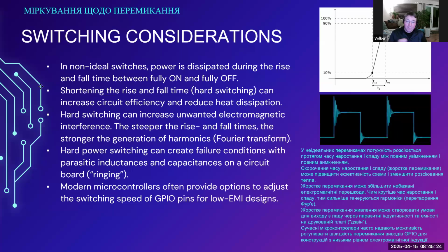In one of the other pictures on the right-hand side, there's an example of what ringing looks like. You can see that the resulting voltage is by far overshooting the normal voltage, the intended voltage of the pulse. So usually when designing drivers with MOSFETs, it is always a good idea to very generously increase the maximum allowable voltage for that MOSFET, to avoid immediately burning it out if something like that happens.